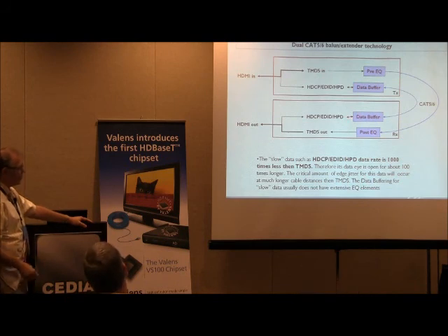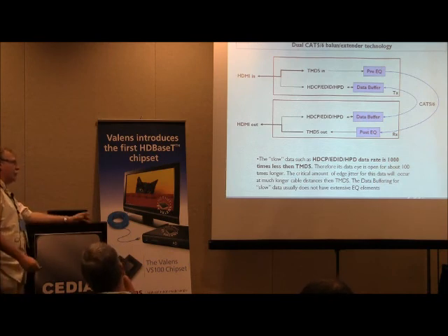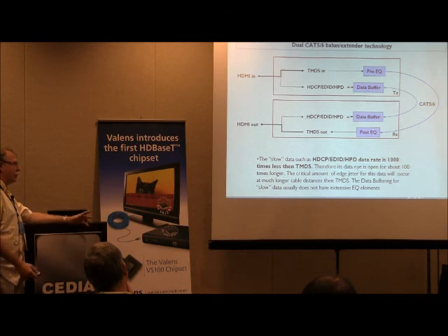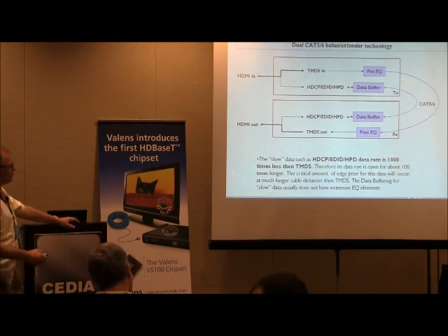You don't need a very powerful EQ to recover that data, but the holy grail is in recovering the fast data. So this is a sort of low-cost implementation. It's widely used today. Some people easily trade complexity against putting in another Cat5 cable. At distances of 100 to 150 feet, and with 1080i 200 to 250 feet, this works well and is used throughout the industry.